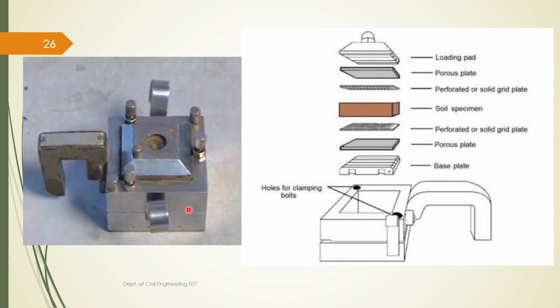Okay, now what I will do is I'll take this shear box and I'll keep it in a shear box container. Okay, just before applying shear deformation I'll be removing these locking pins. If locking pins are there, it will not shear off. The deformation will not be occurring, because this pin is connecting both the halves. So first we need to remove these locking pins in order to conduct the test. What is the purpose of locking screws? They are just for holding these two halves together while filling the soil.